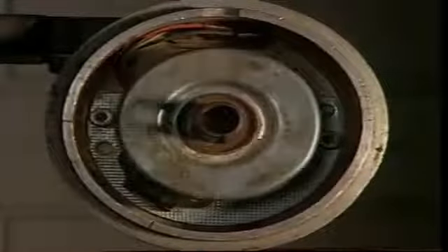When it's used in a distributor, this interrupter ring has the same number of blades as engine cylinders and a corresponding number of windows or gaps between the blades. The magnetic field is strongest when the gap is aligned with the poles. This allows the switch to earth a low current signal voltage that is applied to it.